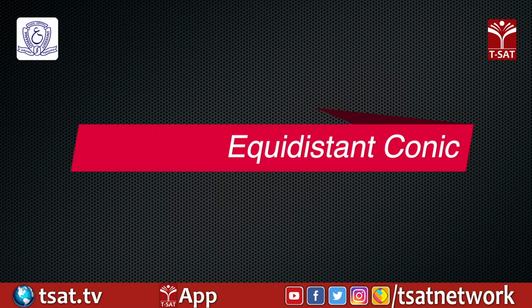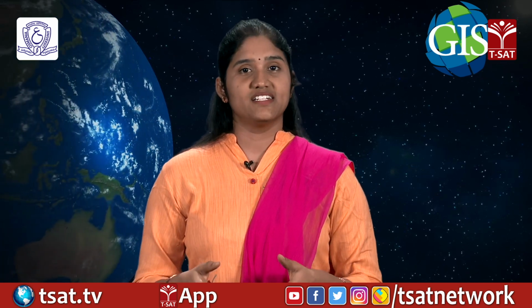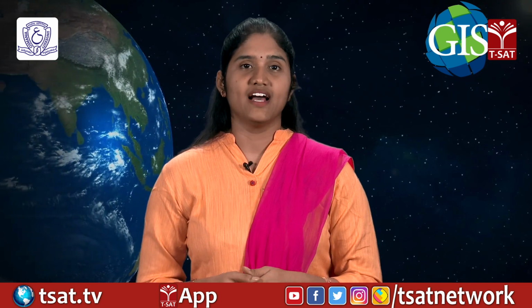Equidistant conic. The equidistant conic projection is also called the simple conic projection. The projection preserves the distance property along all meridians and one or two standard parallels. It uses the same parameters as the Lambert conformal conic.